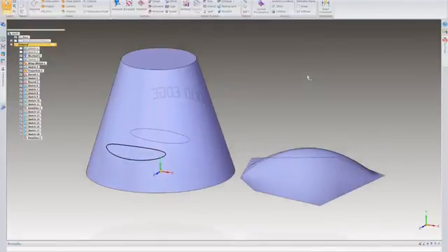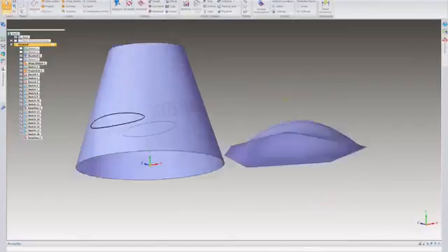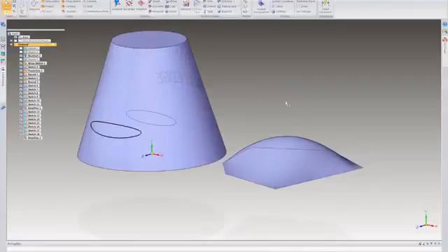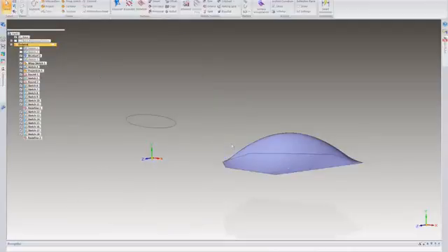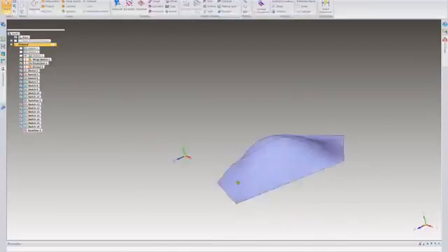Excellent. All right, since I have some more time, let's go ahead and create a solid out of this. So now that we have some surface geometry, of course, that doesn't necessarily show up in the assembly unless you toggle it. If you want this to be a solid geometry, this is a good time to do that. Let me get rid of some of this. I'm going to make this really funky surface a solid. There we go. So that's cleaned up enough.